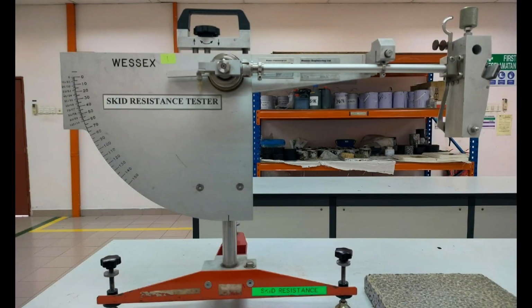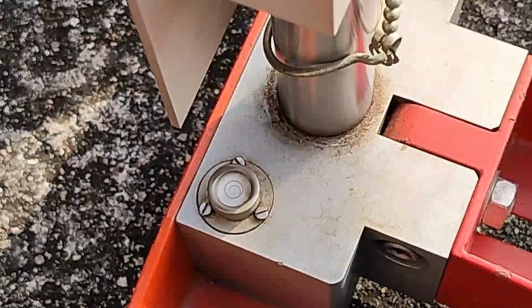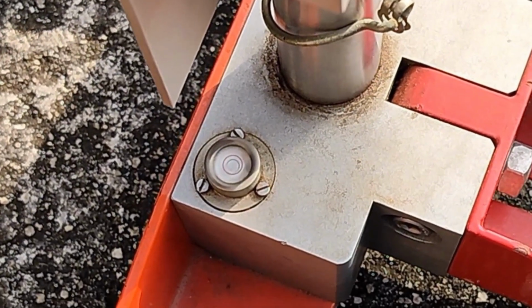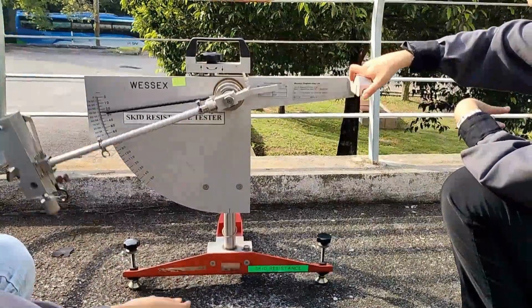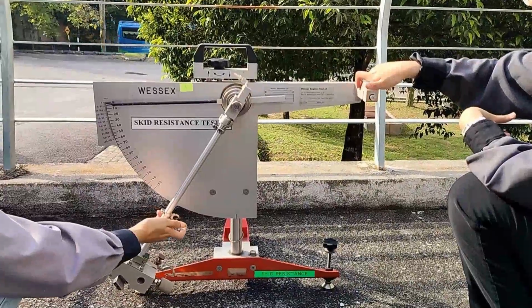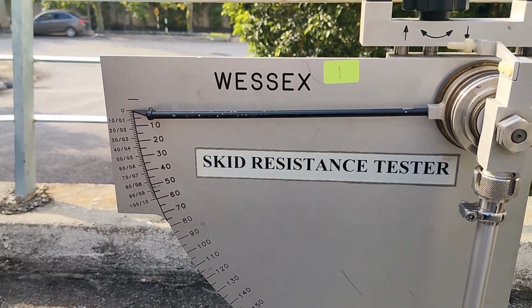With skid resistance, it allows for better grip between tire and road surfaces. Apparatus needed for this experiment are portable pendulum skid resistance tester, scale ruler and brush. The skid resistance tester is set up so that the center column is vertical. This is done by adjusting the 3 leveling screws at the base. Step 2. The height of the pivot needs to be adjusted so that the arms swing freely. Check that it swings right through to the dot 0 on the scale.